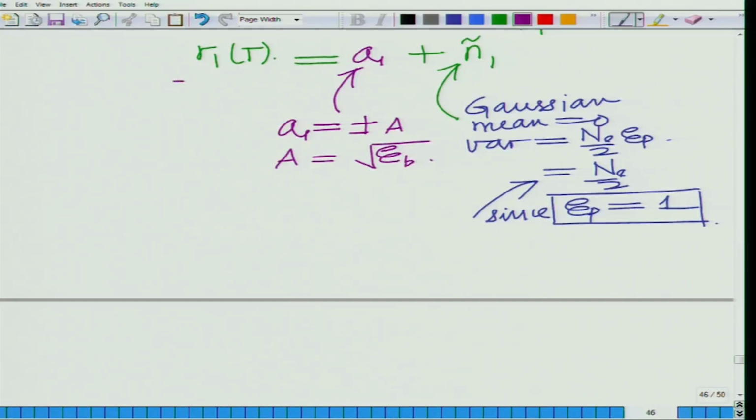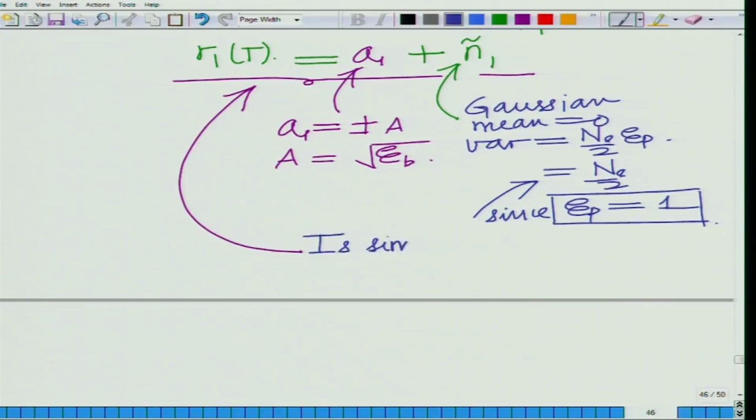So, A1 equals A. This is similar to BPSK. So, after match filtering by H1, this becomes similar to BPSK. Not saying that QPSK is similar to BPSK, but after match filtering by H1 T, which is equal to P1 of capital T minus t, where capital T is the duration or the sampling instant, the output sample R1 T is basically similar to what we have for binary phase shift keying. That is what we have on this branch after match filtering with H1 T.